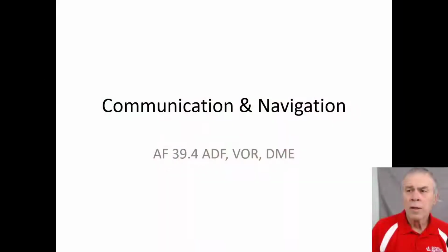This discussion is going to be ADF, VOR, DME. This is kind of in a category of navigation that is ground assisted. There's something on the ground that will usually transmit a signal, and it can be interpreted by the aircraft systems. Sometimes they'll refer to these as dependent navigation systems.